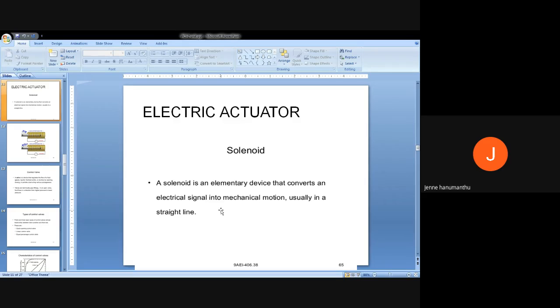Sometimes, that is so called stepper motors. So if you apply electrical signal to this stepper motor, what is the output? Again, a rotational displacement. But remember, the output of the stepper motor, rotational displacement, is not continuous. It is stepwise. Stepwise rotational displacements we are expecting, right? So stepwise rotational displacements. That is the output of a stepper motor.